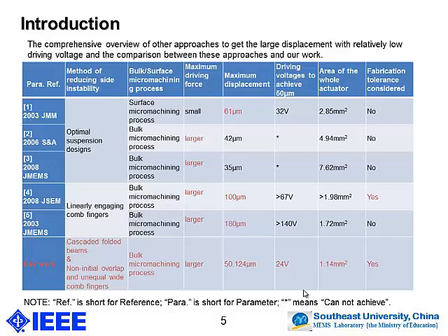And in references 4 and 5, the comb fingers were optimized to have large displacement. In our work, we optimize the folded beam and the non-initial overlap, and unequal wide comb fingers were also used to achieve a larger pull-in voltage.